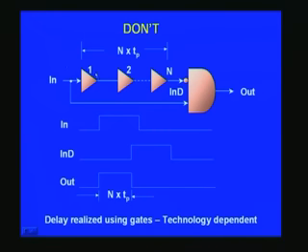For example, Tp is the propagation delay for each of these buffers, let us say. So finally you have a total delay of n into Tp, and that is at this point. This is inverted here and fed here to the gate, and the input is also fed to this gate with a view to get this final output, a rising positive pulse, from the two inputs that we have here.